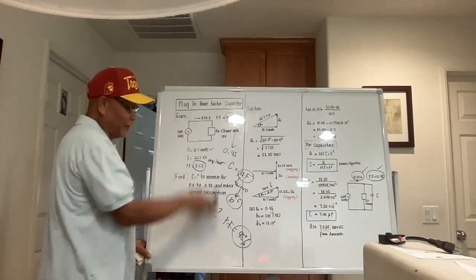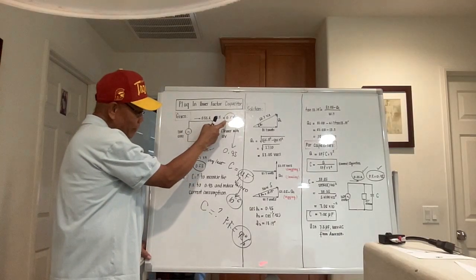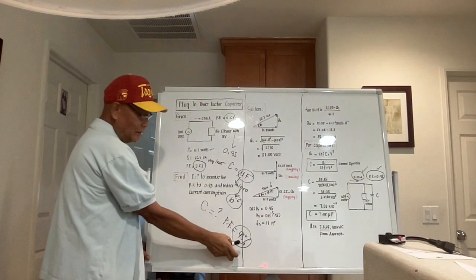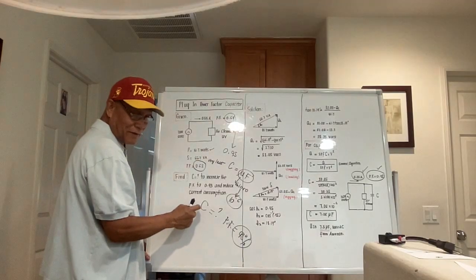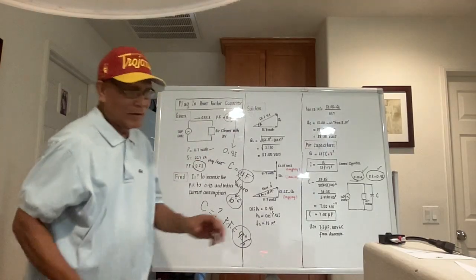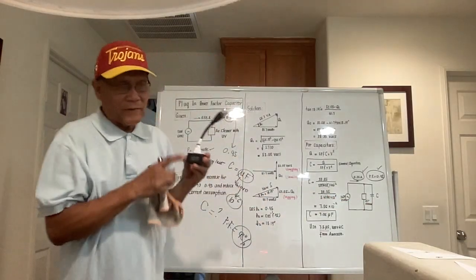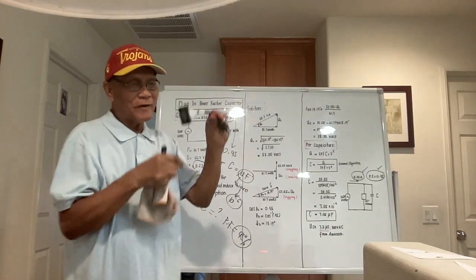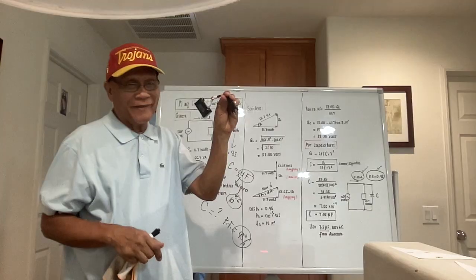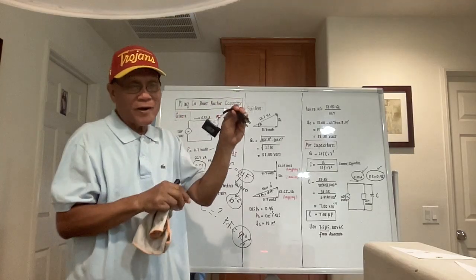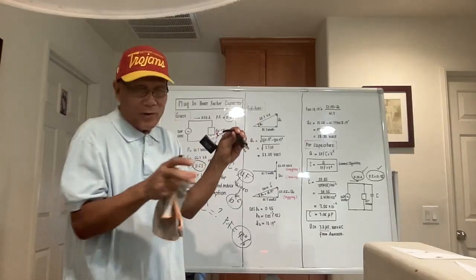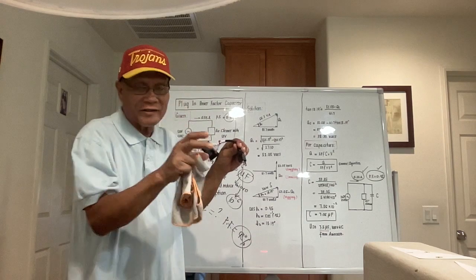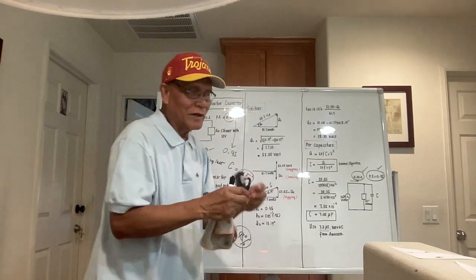So for this illustration here, I would like to increase the power factor of this air cleaner here from 0.62 to 0.95. And the problem is, what will be the capacitance of the capacitor needed? This is the capacitor to be needed. And what will be the value of this one in terms of microfarad? This is plug-in. It's easy to use. You just plug in this one beside the motor load which you are operating, and supposed to be, if the value is correct, you will lessen the current consumption. Okay, let's proceed.